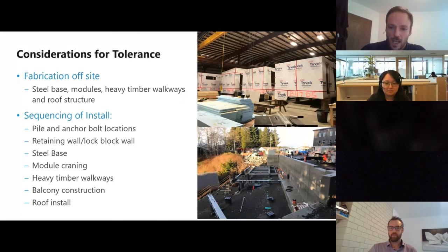So if you look at the bottom photo there, we built that retaining wall, and we took as-built measurements all along there. That was done before the steel base. We referenced those measurements with our site plan for the steel base. Steel base was all done by, they have very accurate machines that fabricate that. So that wasn't an issue. It was the setting of the mods and then also reference to the heavy timber. So the way we had to do this is if you can see there, the piles all had anchor bolts that the steel base would sit on.